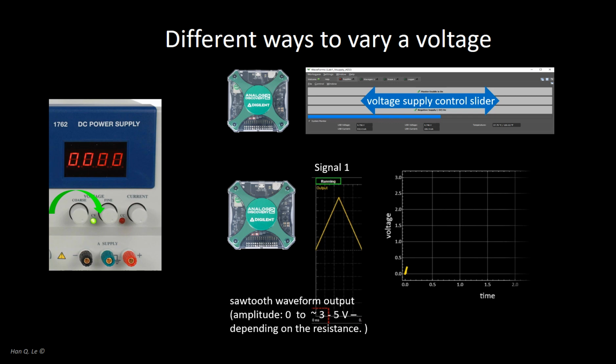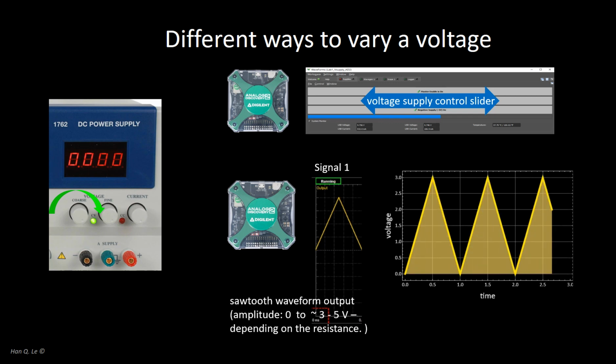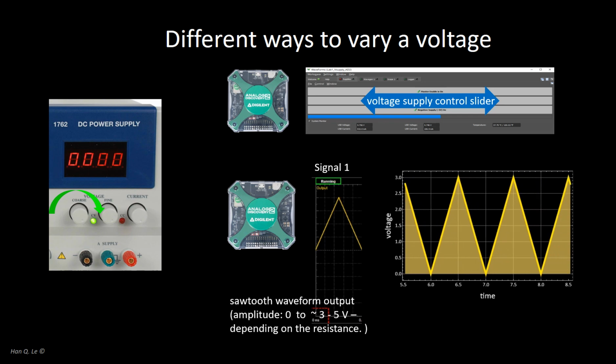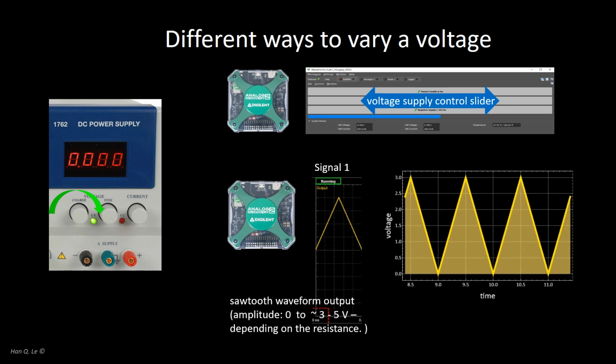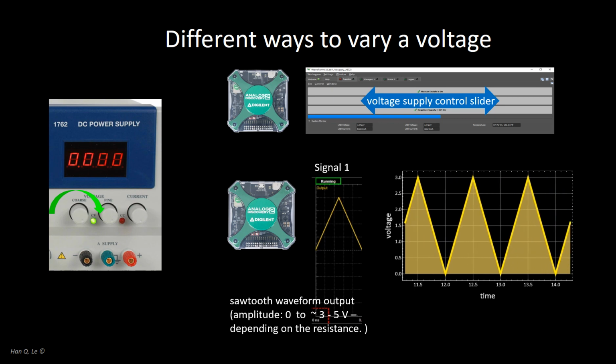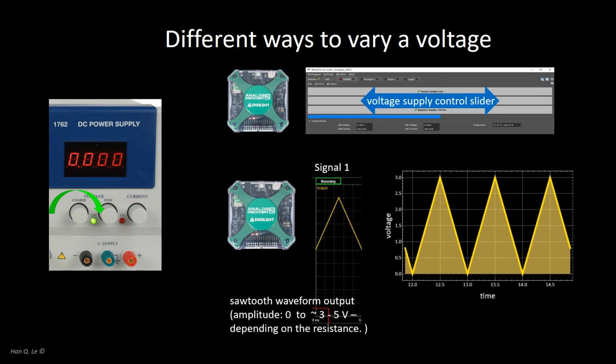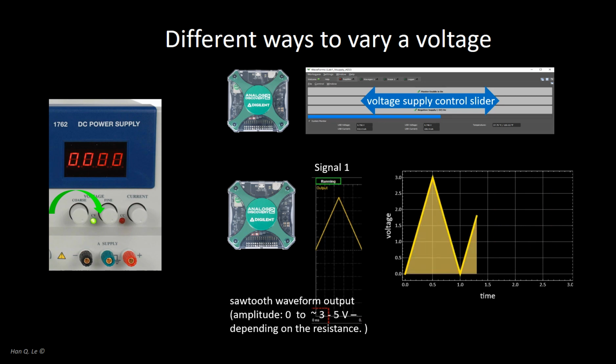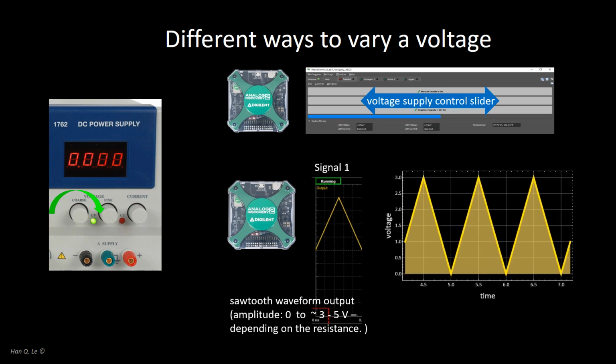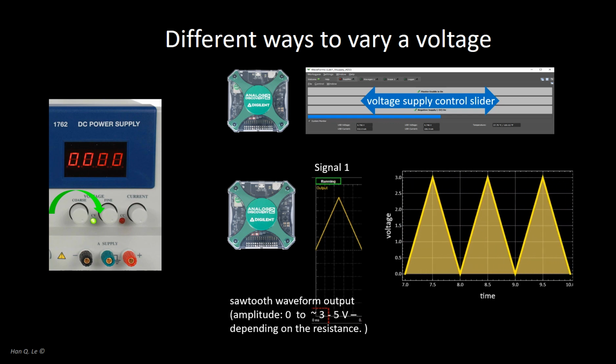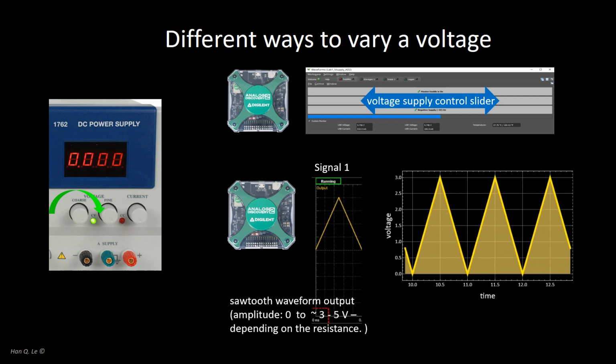The third and most convenient is to program the computer to do all automatically. The AD2 can be set to change the voltage up and down automatically, with no need for manual mouse control, while also recording the voltages. This can be done at very high speed, for example, 1000, 10,000, 100,000 times or more per second. Obviously, this is why we will use this approach not only in this case, but also for many other measurements throughout the course. As an extra note, the varying voltage is also called a signal or a waveform. It is just another word for any kind of time-varying voltage.